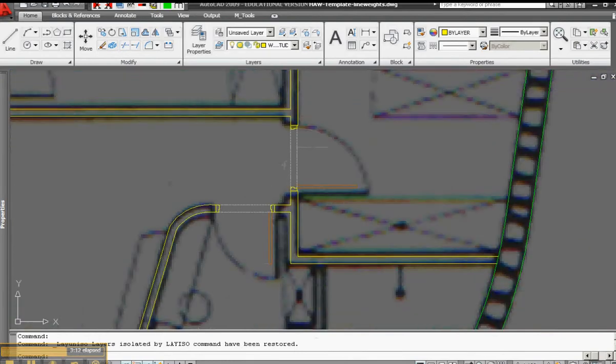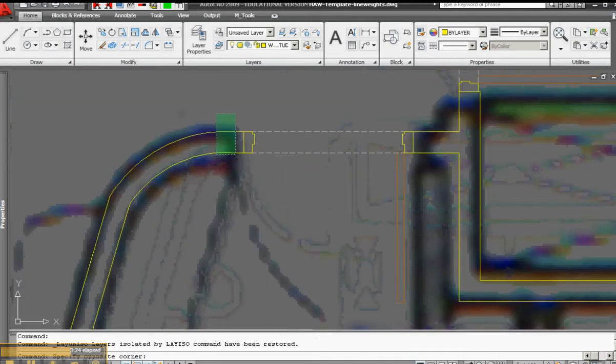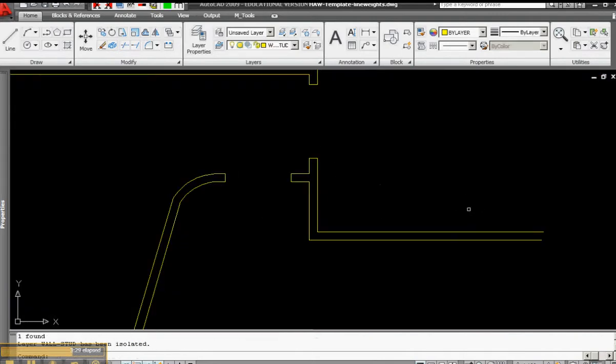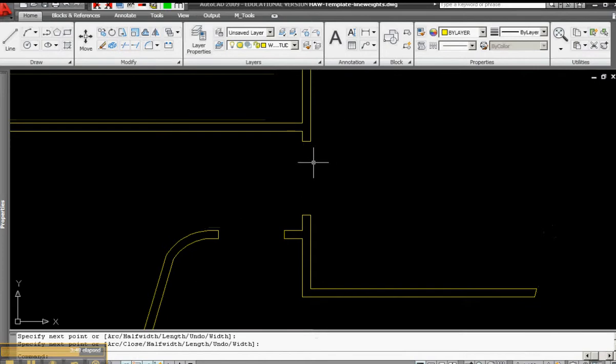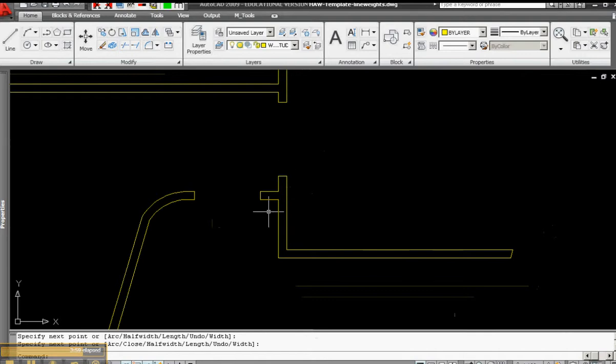It's not as automatic as ArchiCAD, Revit or something like that. It doesn't trim the door out of the wall automatically, but it has advantages and sort of other advantages in that when we take this stuff into whatever it is, Rhino or 3D Studio, if this is a joined polyline, it'll extrude and it'll cap in one go, whereas some of those other, whatever it is, AutoCAD, it'll be a 3D model, but it'll have all this extra information that you don't need in a 3D model for sort of composition, for rendering stuff.